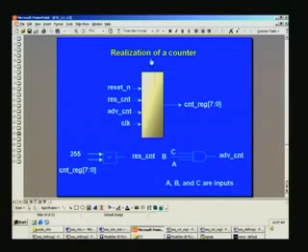The counter is quite simple. You have a reset count, then advance count, then overall reset is there. So when counter equal to 255, then this reset count is applied, and this is power on reset. You advance, that is increment the counter, only if this condition is satisfied, which is ABC, right? It's quite simple, and out comes counter register, and a counter next was also used inside.